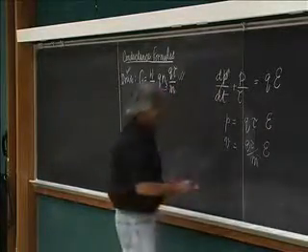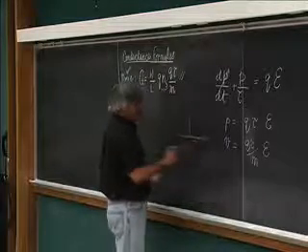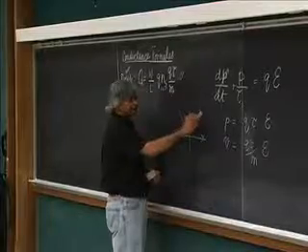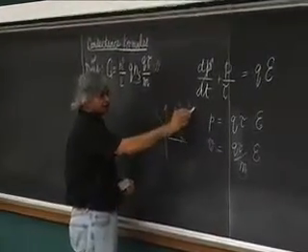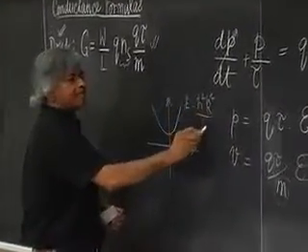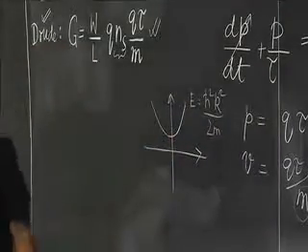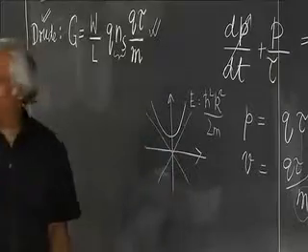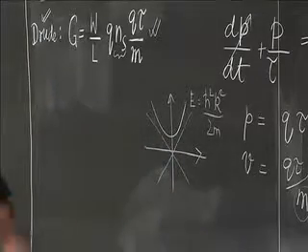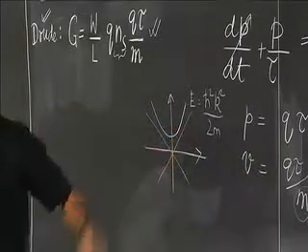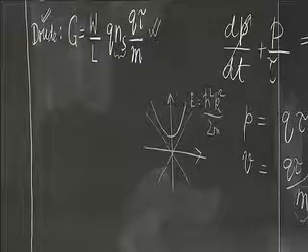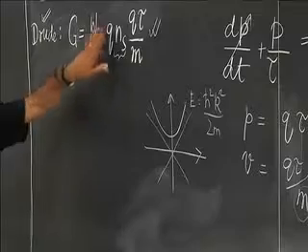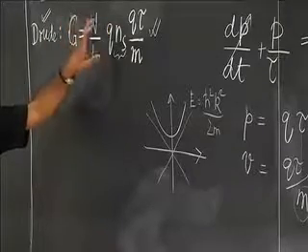That is, when you look at the EK relationship, as you know, usual semiconductors have a parabolic relationship which you write as E equals h bar square k square over 2m. But that's not the way it looks in graphene. It looks linear. It looks something like that. And then, of course, it's confusing because you don't quite know how to extract a mass out of that. So that would be the first problem you'd run into in terms of trying to apply this equation to graphene.